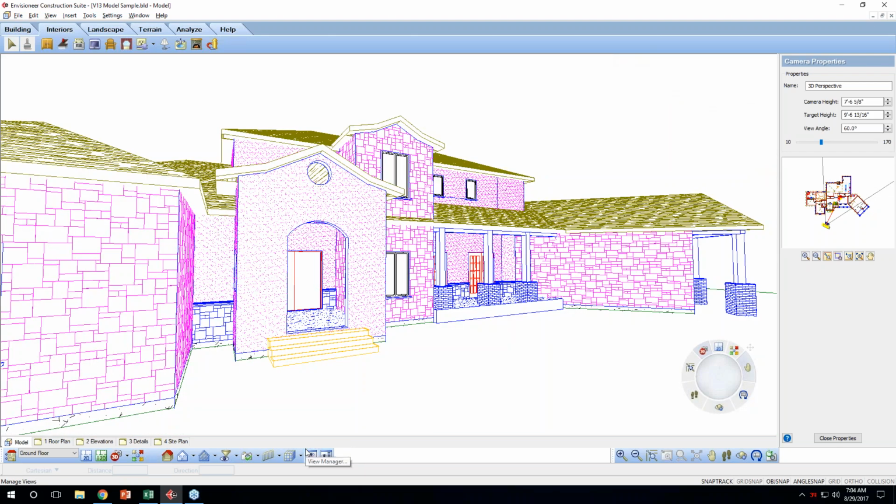and I'm going to put this into a hatch pattern view. When we're putting in hatch patterns for walls and columns and different elements, before the hatch pattern was put on the same layer as the elements. So the hatch pattern for walls was given the same properties as the wall itself. So when it was transferred over to working drawing sheets, it had the same line weight and line color.